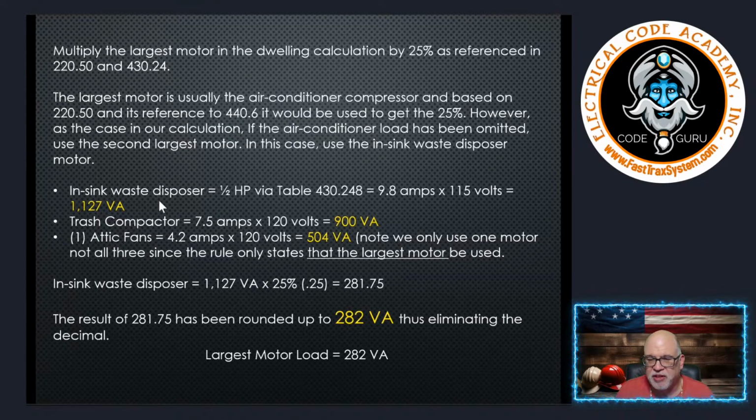And again, people say, well, why did we not use the AC? Because that is the largest motor, but we discounted that entire load when we did AC versus heat. So it's gone. That's why we're hunting for the next largest motor, and that's what we got, the in-sink waste disposer. That makes sense, I hope. And if you don't believe me, you have to have a leap of faith here. That is exactly how it works. I've been teaching this for 38 years. That is how it works, okay?